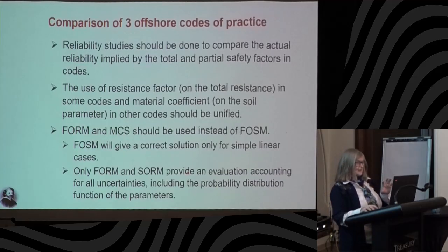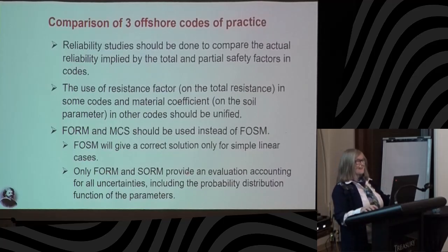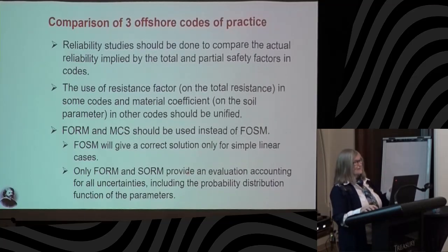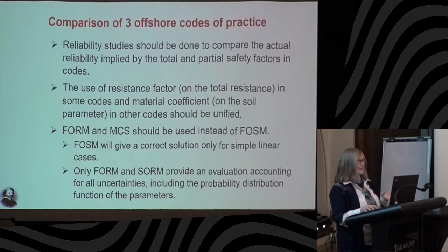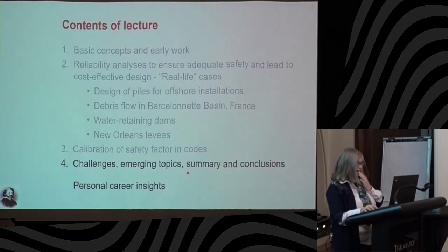Maybe I'll skip the conclusions, but I think it's very important to understand that the safety factor is just not the solution to all cases. Because the code gives a constant safety factor, but reality is you have very different cases, very different types of loadings, very different models, and then the failure probability is very different.